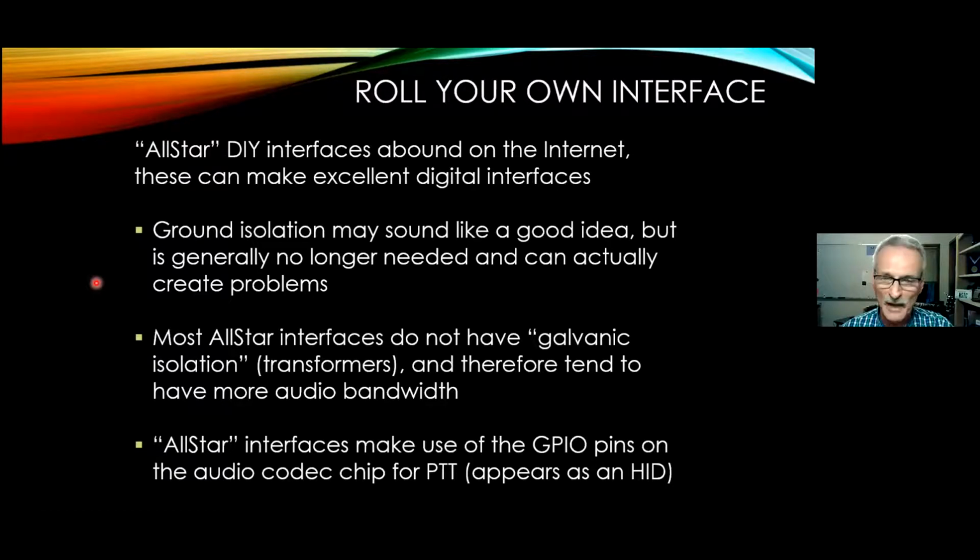To get the bandwidth that you want, you need a good transformer, and I mean a substantial transformer. You have to have really good permeability in the transformer, and that means it's going to be large, with a lot of copper in there, and a lot of nickel and iron to do that. And it's just not going to fit in your interface.